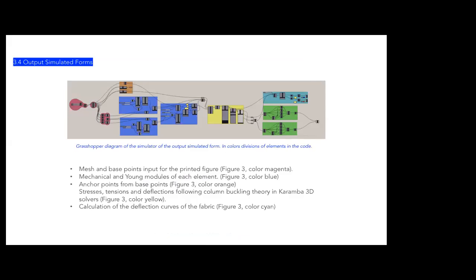Initially, to mechanically simulate the static condition of the prototypes, the base geometry of the membrane and input pattern were parameterized and the fixed vertices from the flat parametric surface were extracted. From this initial setup, a 5-step computational definition was made. The guiding key of the form finding process within the simulator is the assignation of mechanical reactions to each anchor point in the input pattern, similar to the reactions that we'll have in a physical prototype.